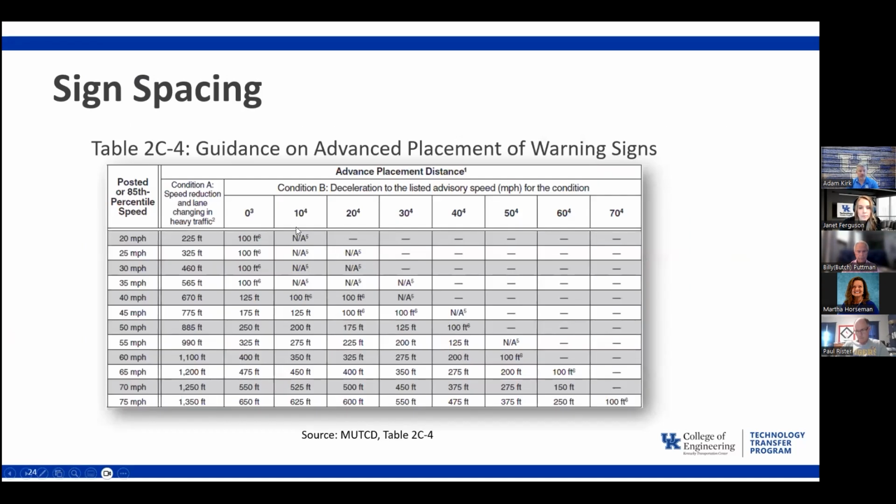And so, I'm not quite sure why they did this, but most of the time, our speed limits are 25, 35, 45, 55, and our advisory speeds, you got 10, 20, 30. Safest thing to do is to round down. I think that's just about anything in engineering. We'd rather provide a little extra safety, factor of safety by rounding down. So if I've got an advisory speed of 15 miles an hour, which would be in between here, we would round down and use the 10. So sorry I missed that question there, John.